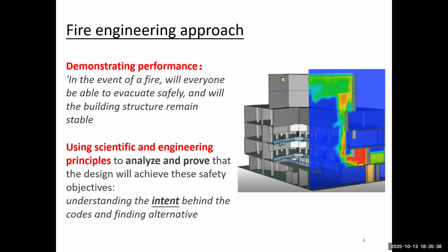So FEA, also known as the fire engineering approach. Let's briefly look at this second approach. This is a fundamentally different way of thinking. It moves away from simply following a set of rules, and instead we focus on demonstrating performance. Instead of asking, does my design meet every single clause in the code, the fire engineer will ask, in the event of a fire, will everyone be able to evacuate safely, and will the building structure remain stable?